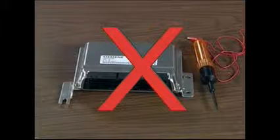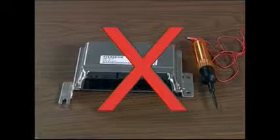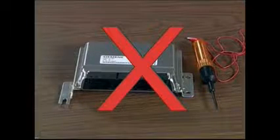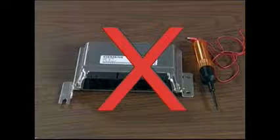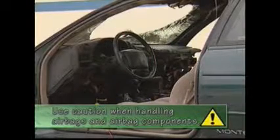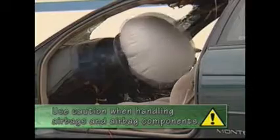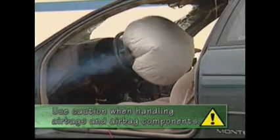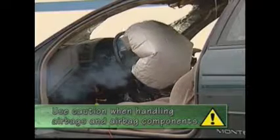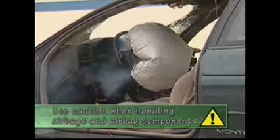Never, and we mean never, use a test light on any part of a circuit that leads to an electronic control unit or on a supplemental restraint system airbag. The use of this test can cause the sensitive circuits in an electronic control unit to melt, or they can cause airbags to deploy. Serious personal injury can result from ignoring these cautions.